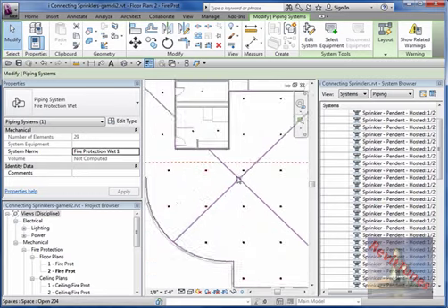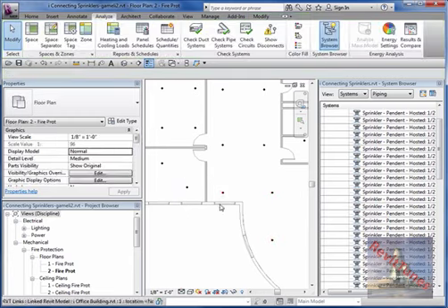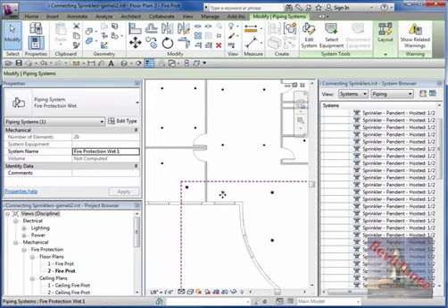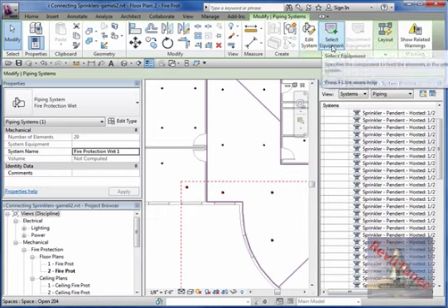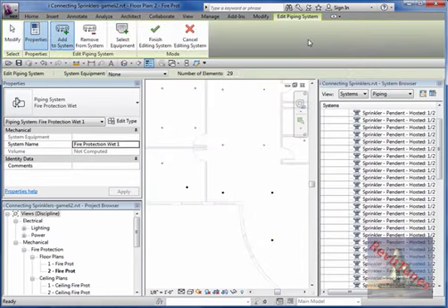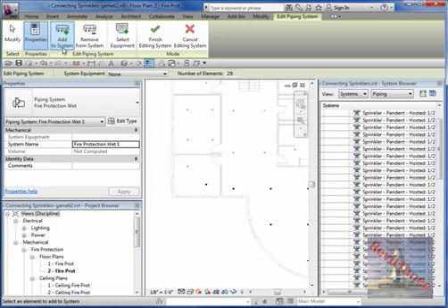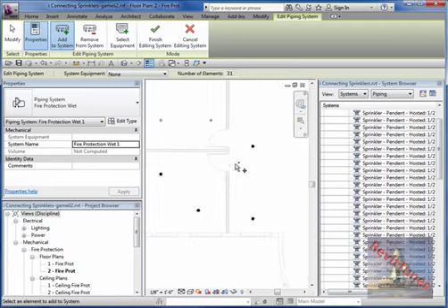And let's say you forgot to put one of these sprinklers. By selecting the system the way I did, I hit tab, then click, you see these new buttons right here. One will give me a chance to add equipment, and this to edit system. And one of the things that I could edit is, if I choose the plus sign, add to the system one more sprinkler, I could add it. Take a look how I added those two. That's why it removed the gray out.